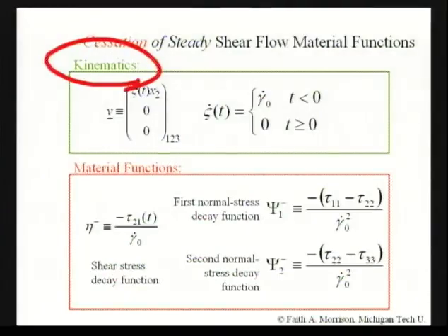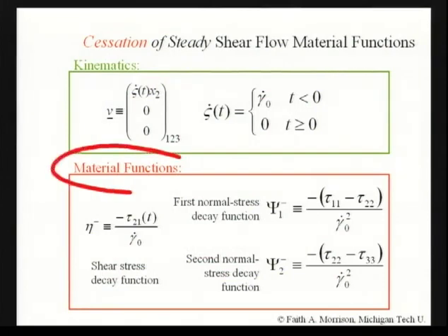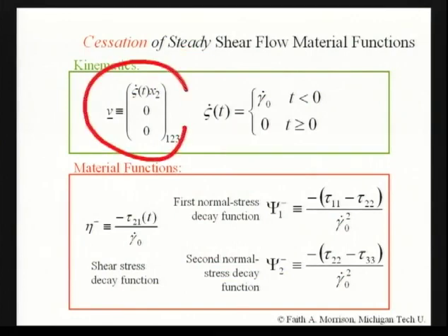We can do other non-steady flows besides this startup one. And we've got a bunch. And I can assign you these as homework. I can say, take Newtonian fluid and predict it for all of these flows. Because for every flow, I'm going to give you the kinematics. I'm going to give you the material functions, and you can predict them. So this is steady. This is cessation of steady shearing. Here again is our velocity field. Here it's shearing for all times, and then suddenly we stop.